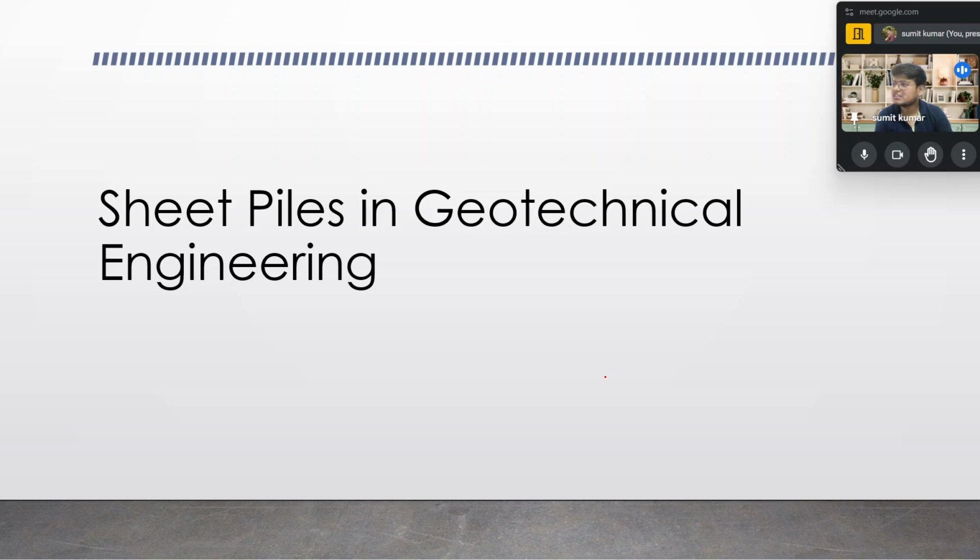It is only for dry sand. For wet sand and for OCR, some other values are also there, which are mentioned in the standard books. But in general, when we calculate earth pressure at rest, we consider the dry soil condition only, because either the active or passive state gets developed in one way or the other. In the real field, different conditions could also be there, but in general we say it is the dry condition.